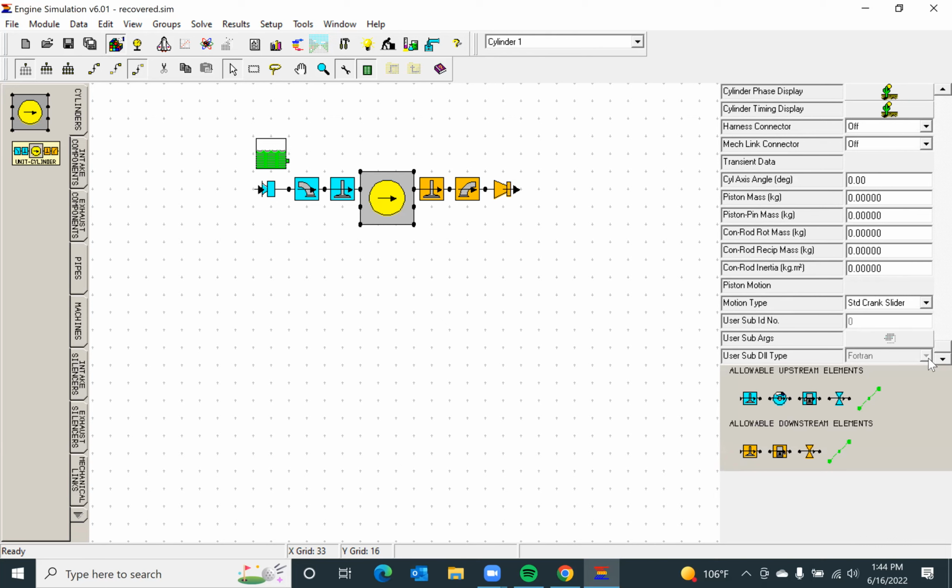About 10 years ago, I worked on a research project where we came up with this idea where the piston and the connecting rod are made up of one solid piece. So there is no articulation. So we used a hypocycloid gear mechanism that would take the translational motion of the piston and convert that into rotary motion. And the kinematics of that mechanism is completely different than the slider crank. So you have an option of changing this mechanism.